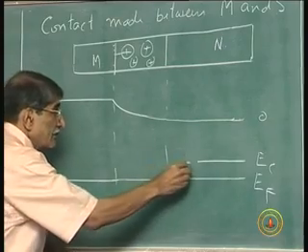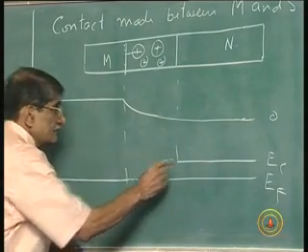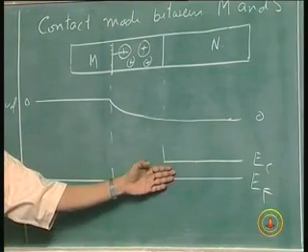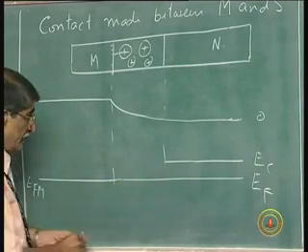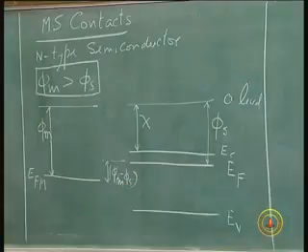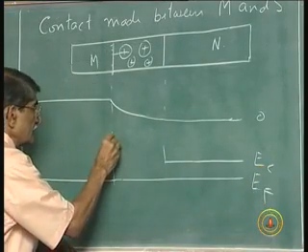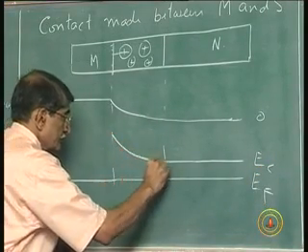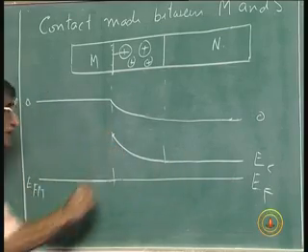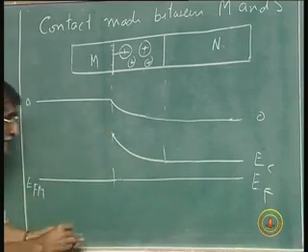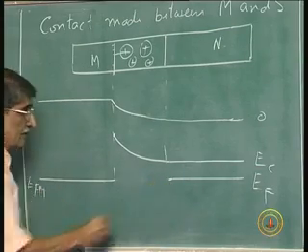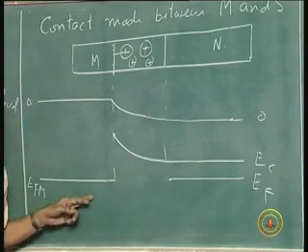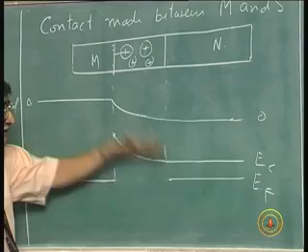Okay. Now, what about this Fermi level? You draw it only up to that point. In this portion you do not draw it, because it is not an equilibrium situation there. So, you stop there and call it the, oh I am sorry, this is the conduction band. Conduction band, you draw all the way up to this point flat, from that point onwards like this. So, that is the conduction band edge there, and the Fermi level now you do not draw here, you stop there, it is okay, because you talk now of the quasi Fermi level here.